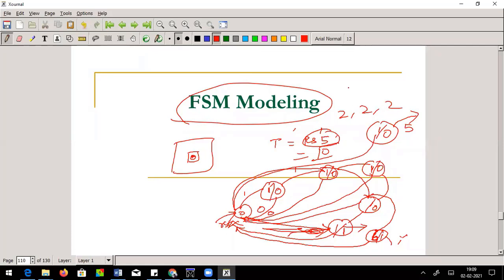Okay, that fellow is not giving like this. He is giving ₹1. Now you need to go like this. When it recognizes that it is ₹2, you need to come here. Another ₹2, you need to come here. Another ₹1 more, you need to come to this particular state and give the ticket. Okay, he is not giving like this, 2, 2, 1. Instead, he gives 1, 2, 2. Then you need to alter your state diagram. You see why I'm saying the wild possibility of making a state diagram.